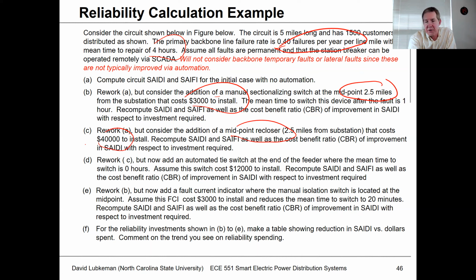So what's going to happen when I have a fault up here? Basically, the circuit breaker is going to lock out. What we can do in this case is we can actually have some logic that very, very quickly opens up the recloser, closes in the sectionalizer, and basically what's going to happen is we don't see an event at CD anymore. So what this would mean is we'd have to have some pretty fast logic.